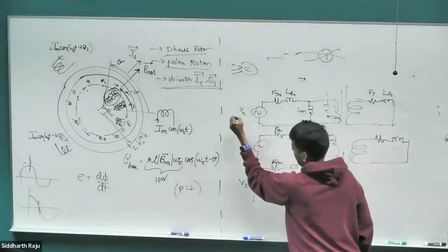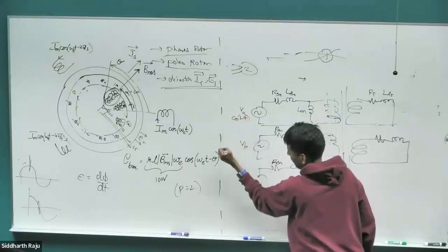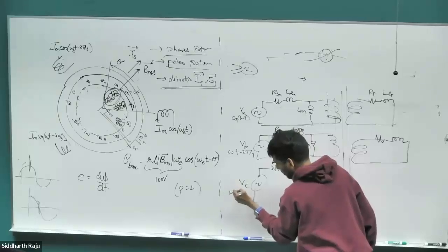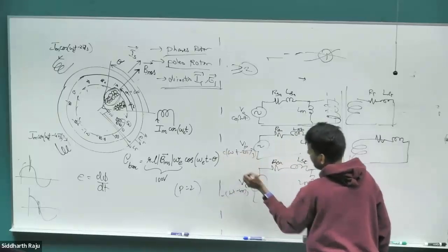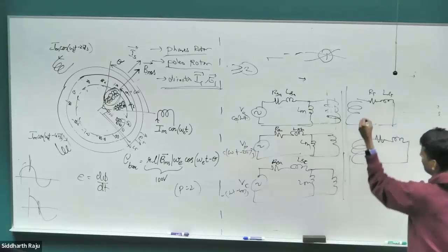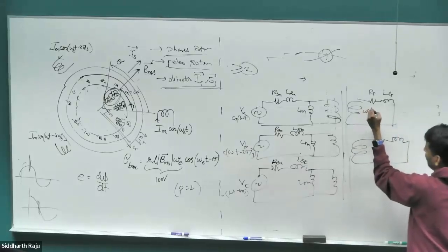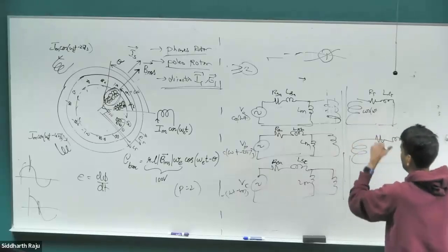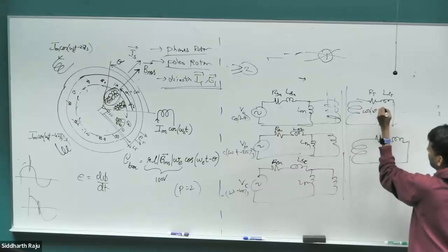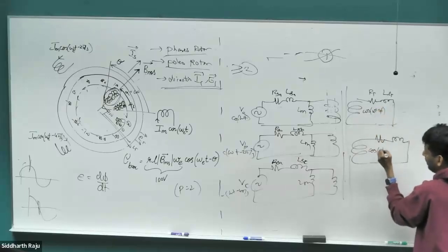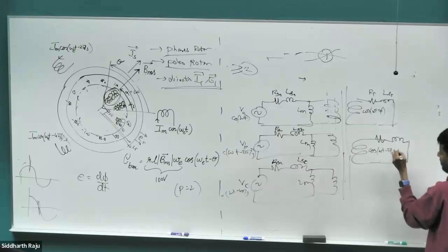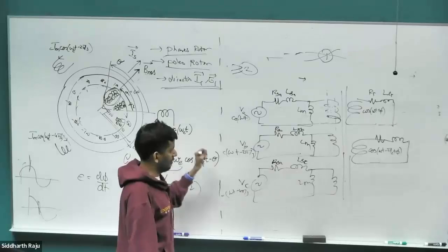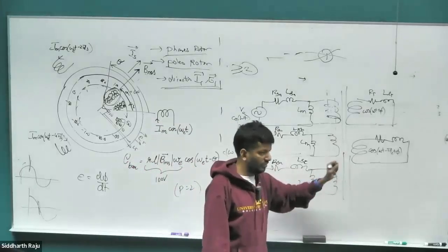So mathematically you can create this model. So here the voltages would have been cos omega t, let's say. This would be cos of omega t minus 2 pi by 3. This would be cos of omega t minus 4 pi by 3. On this, you can model it in such a way that this comes out to be some cos of omega t. Again, we haven't considered the case where the rotor has yet started rotating. It's all stationary, plus some phase phi. And this can be cos of omega t minus pi by 2 plus phi. Mathematically, you can absolutely model this and there will be nothing wrong. You can derive all the equations that we are going to be doing next on Friday using this simple model.